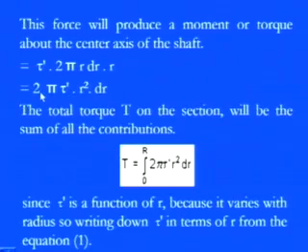So you see, you can simply compute this torque for the whole section, because whatever moment we are gaining is just for this small section which has a thickness of dr. Now if I am saying that this is valid across the whole section, then the total torque on this circular shaft is nothing but the sum of the contributions from these small sections of dr.